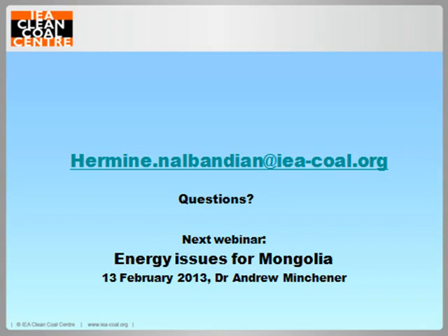I have a question here saying, please explain the effect of furnace temperature on trace element emissions. As shown in the figure previously, as the temperature reduces, vaporization of the element is greater, and the smaller the particle, small particles have greater amounts of trace elements like mercury, arsenic, and selenium. I'm trying to go back to that figure, but I'm sorry, I can't find it right now. I will send you a detailed answer to the question.